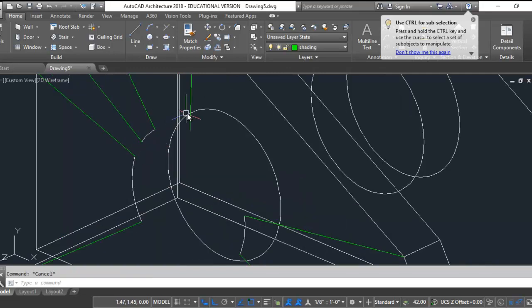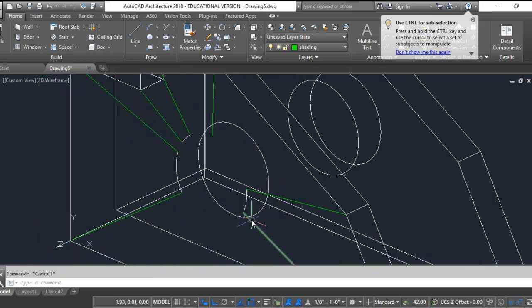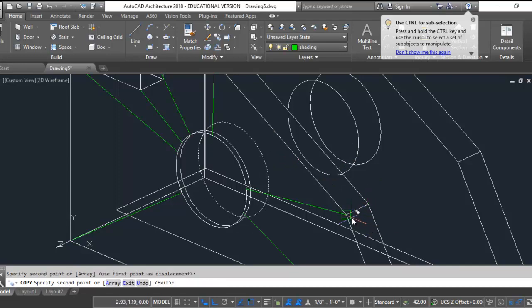Now to finish our circle out where I don't have circle, what I want is basically a segment of the circle for every piece of the pie for rule surf to work. What I'm going to do is copy this back circle using maybe this as a base point from here to here, and now I can finish trimming out what was left.